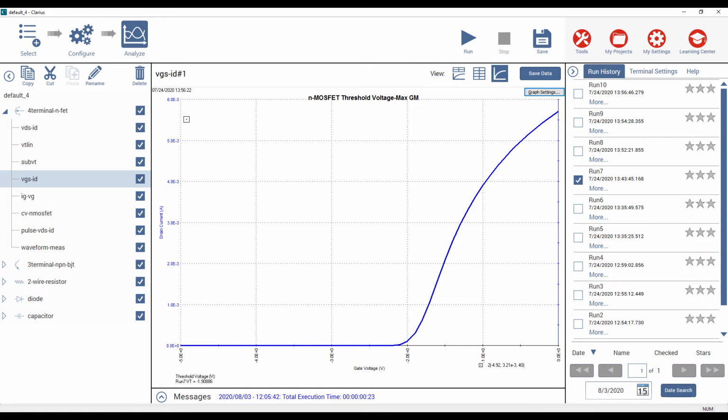And we can see that the threshold voltage, if we take it to be the x-axis intercept, is around -2 volts. What that threshold voltage is that you want to report is something that needs to be defined quite precisely. And you can see here between the semi-log plot and the linear plot, there are some differences in how that threshold voltage can be defined and interpreted. Nonetheless, there is no doubt that this is a depletion mode device.